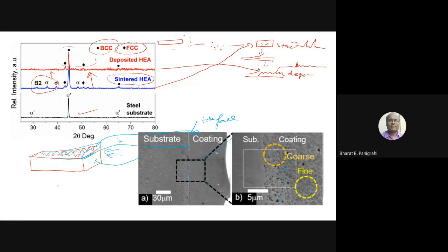In addition, we can also see a very diffuse layer. The actual interface is extremely smooth. In a deposited layer, there is a possibility of a few very small pores, less than half a micron, 200 or 300 nanometers, in a few places, but otherwise you will see mostly uniform structure.